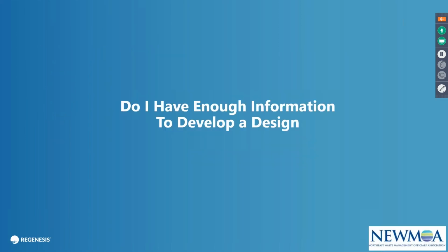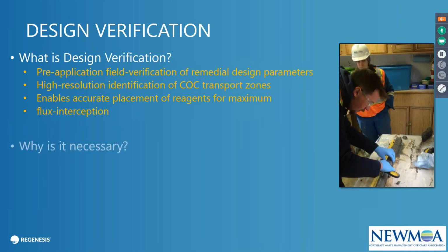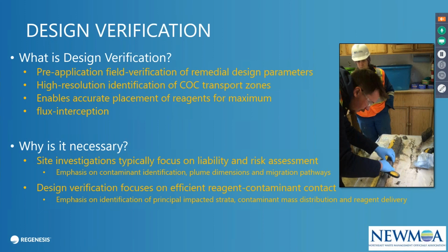So, in that next step, the question you also have is, do I have enough information to really develop that design? And by design, I'm talking about the actual application itself. Because a lot of data that's collected is for site investigation. And so with that, you're looking at liability or risk or what's the extent of my plume. But what we're looking at for a remediation is we're trying to focus on efficient reagent delivery and getting it to the right place.